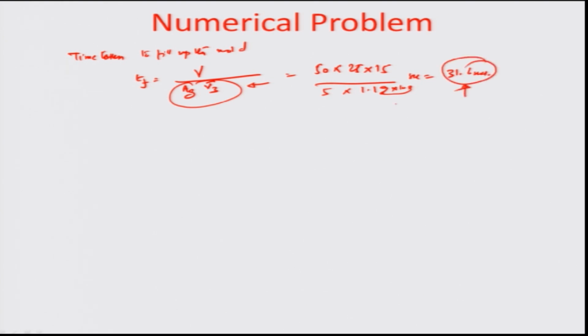So, that is the new filling time, and you can see that the filling time in the ideal case was about 43% less than the case here. So, the filling time definitely has increased, and that is because of the energy loss which happens because of the bending, the different fittings, the wall friction and other issues.